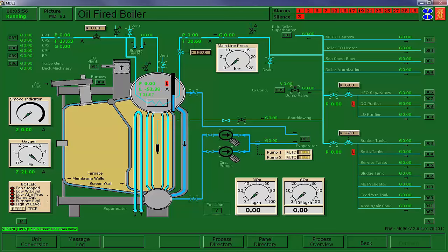We're not going to run the circ pumps. We have no waste heat. We're not going to be running that system, but again, on the initial lineup of this boiler, I would open the inlet and a return to prevent us from forgetting those as we move down through the exercises. All right, so we're ready to light.